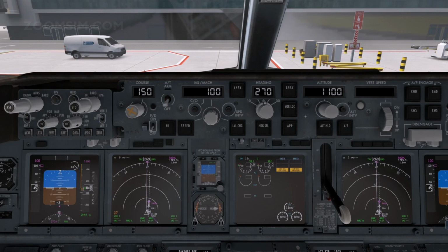In the VOR position, the following information is displayed: VOR navigation information, reference VOR receiver, frequency, course, DME, and to/from information. In the map position, the following information is displayed: FMC generated route and map information, aircraft position, and heading and track. Waypoints including the active waypoint within the selected range and VNAV path deviation.